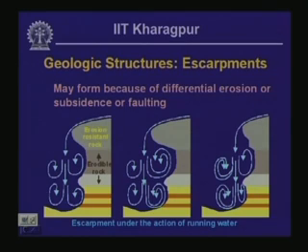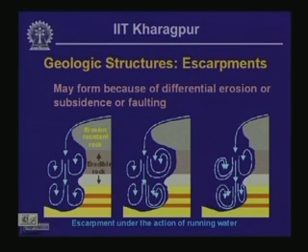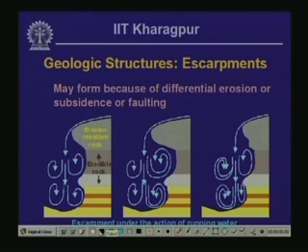Here we have got an erosion resistant rock near the surface, and on top of it flows a river, and that erosion resistant rock is underlain by relatively softer erodible rocks. So, what happens is the splash, the water that splashes while falling like that, causes the layer underlying the erosion resistant rock to erode and recede, and because of the recession of the erodible rock, an overhang is generated in the erosion resistant rock, and that overhang eventually gives way.